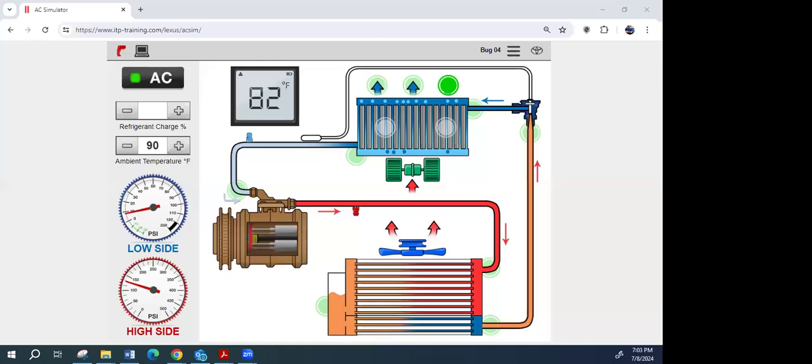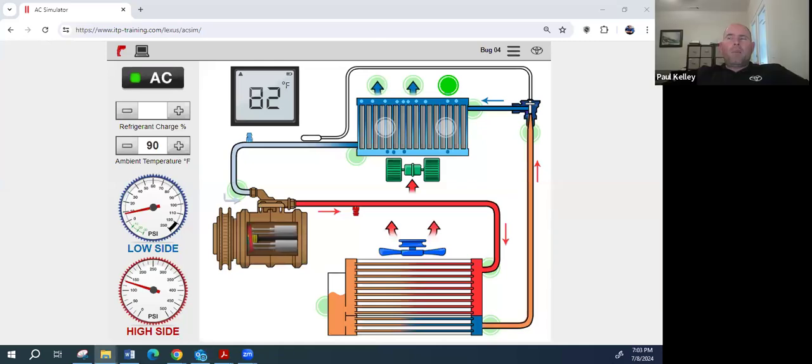Expansion valve. Well, how are we gonna check that? Like, what tests can we do? I want to do tests more so than replace parts. Oh, Renee says in the chat, the low side's too low. I agree. If we put the gauges on there, that low side being at a 9 or an 8, and that high side, well, that high side might look a little bit low too, but that low side is like really low. It's kind of interesting.